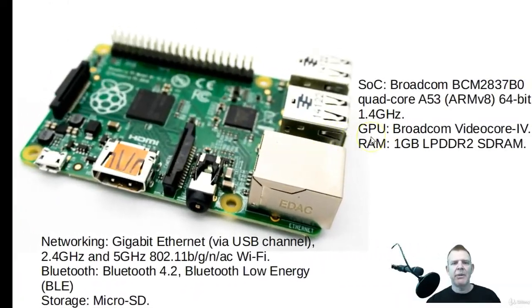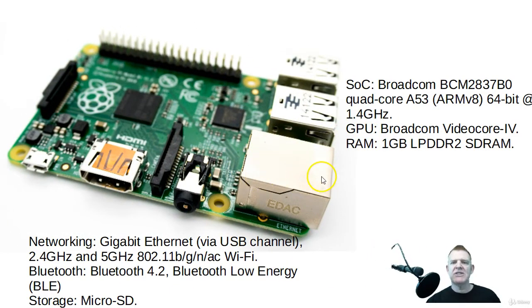Okay, so let's talk a little bit about the Raspberry Pi. Of all these specifications, the one to pay attention to is that it's the ARM A53 processor this board is based around. This means it's a lot closer to an actual PC or Mac than it is to an embedded system. This is an application-level processor. So what that means to us is that this chip and these peripherals hold their own operating system. Unlike the previous truly embedded systems with those Espressif boards, we're not programming an operating system over bare metal here. This already has a Linux operating system and you can get it in different flavors running on the board.